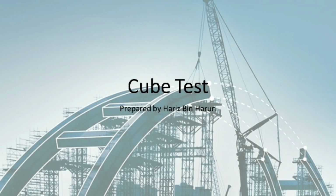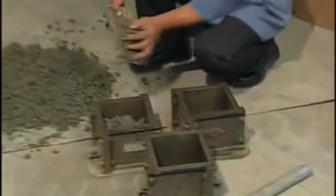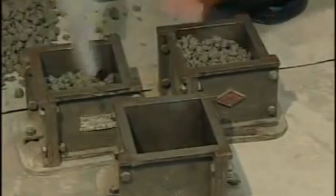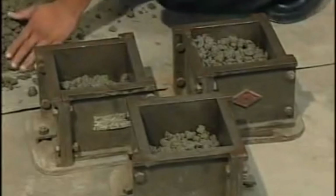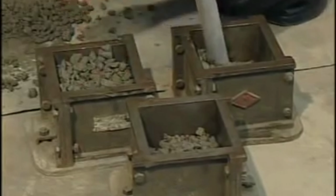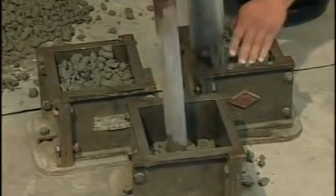And then before we concrete the wall panel, we need to do a cube test. So what is a cube test? The concrete cube test is a compression test carried out on the concrete cube after 3, 7, 14, or 28 days of casting. Concrete cubes are cast and kept for water curing, and then they are tested in the civil engineering laboratory on a compression testing machine.